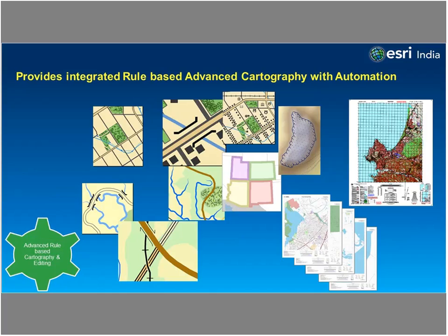Now this cartography we are talking about is not just plain simple polygons and lines, but if you look at the middle of the slide here, these are rules with respect to flyovers and bridges. A flyover has to be shown always on top of the roads instead of below the roads or crossing the roads.